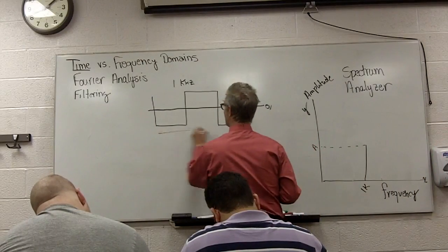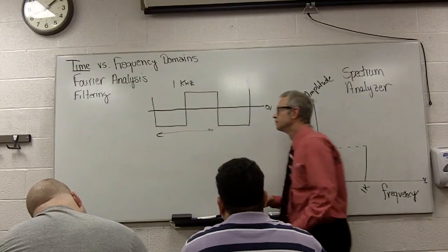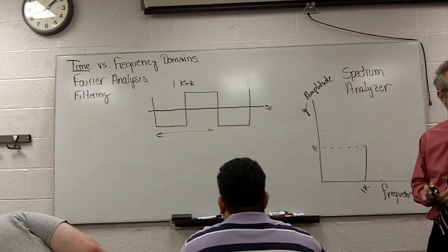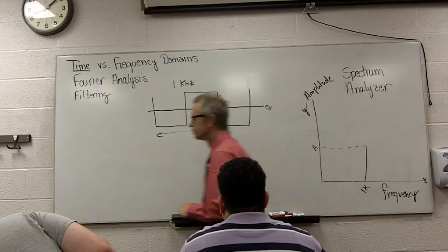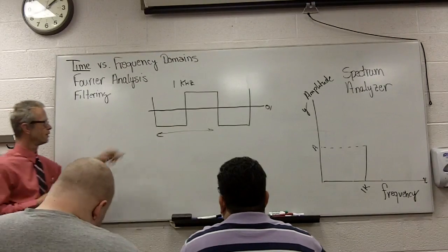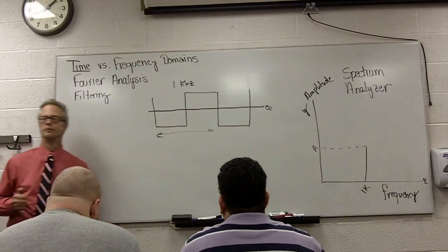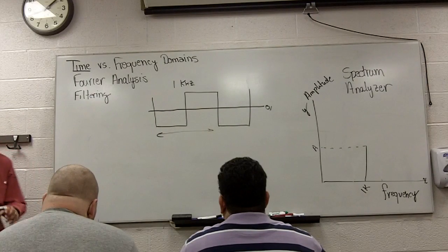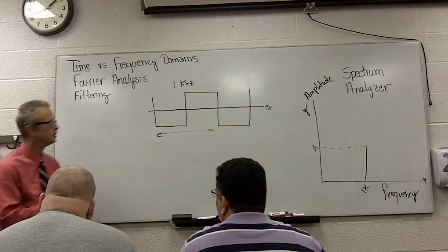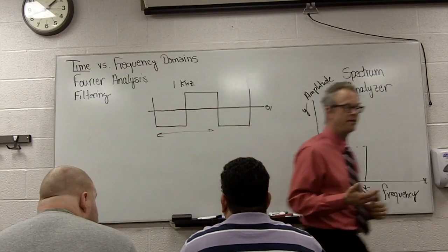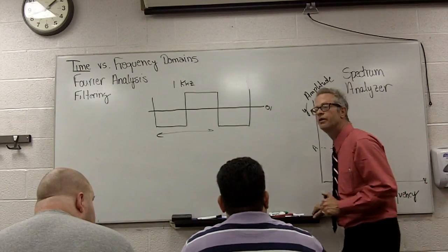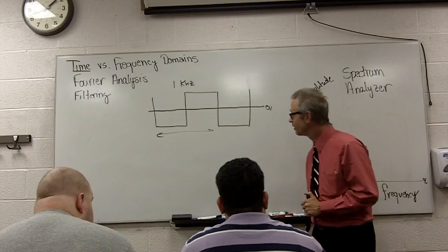That means that this amount of time is how much? Well, if the frequency is 1 kilohertz, what's the length of 1 cycle? Did you do a formula that says that the period of a waveform is equal to 1 over the frequency? Yes. The period is 1 over the frequency.